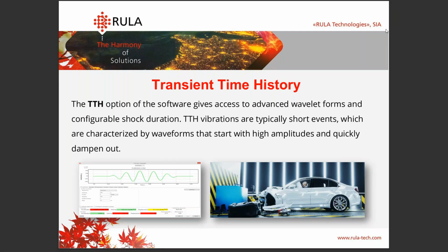The software forms a shock accelerogram by multiplying the base signal by an envelope. As the base signal is always formed in the range from -1 to 1, after multiplication the acceleration by module will not exceed the envelope. The envelope, together with the base signal, provides smooth rise of the signal at the start of the accelerogram and smooth signal fall at its ends.